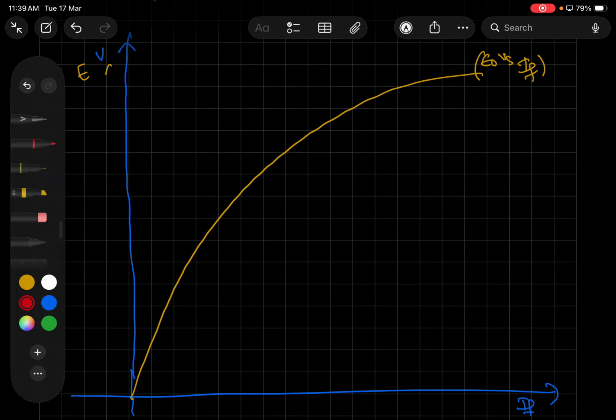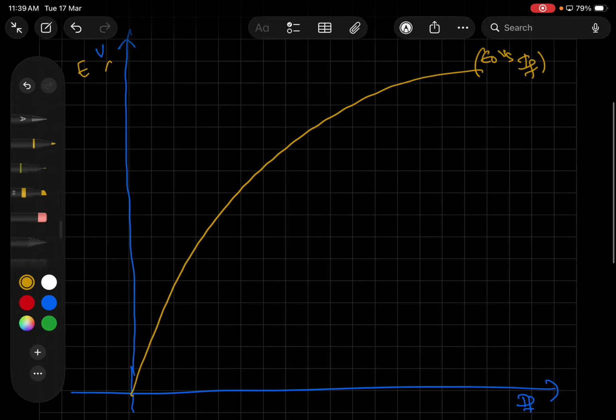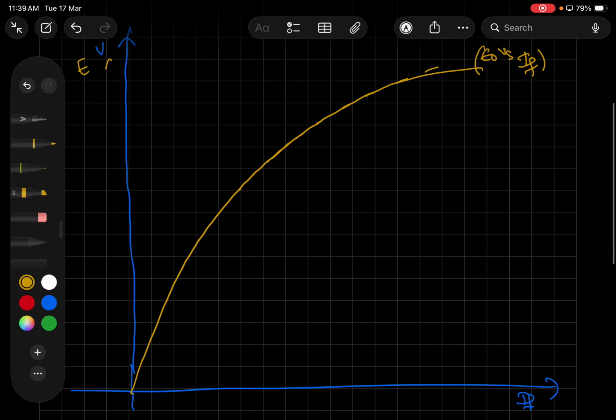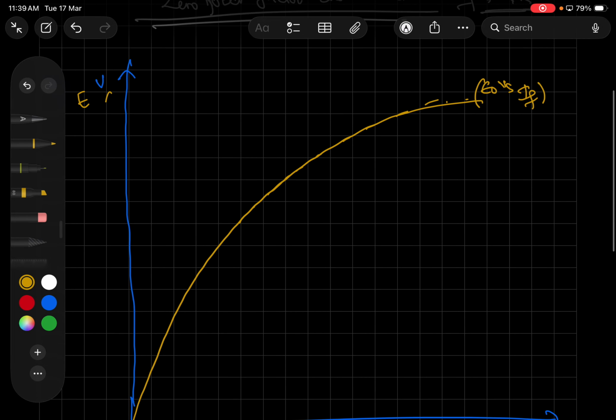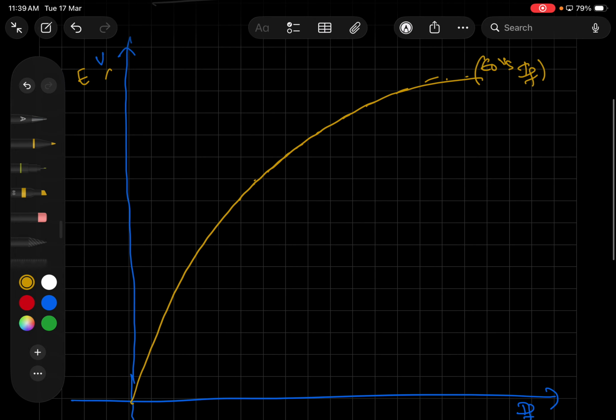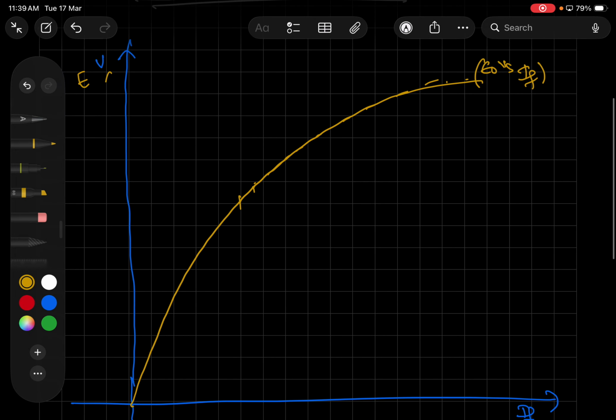What is the tangent, or air gap line? If there is no saturation, the characteristics would be linear. Up to some extent, up to 100%, the characteristics are linear, but beyond a certain point the characteristics bend and droop. It's because of magnetic saturation that we do not get completely linear characteristics.